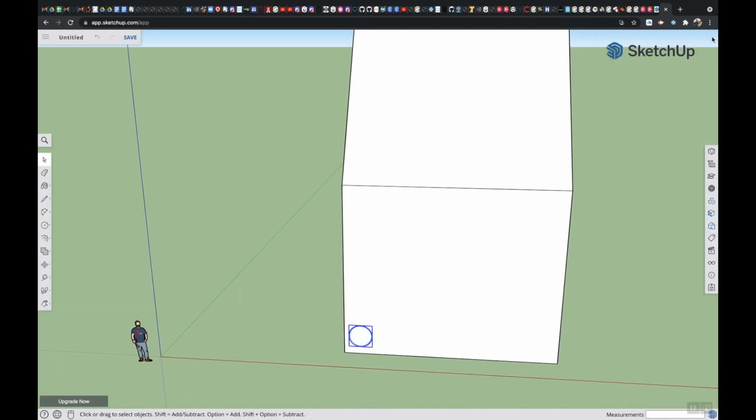Once you've done that, take the move tool and move this all the way across. As you do that, since you're using Windows, you're going to use Control, and I think for Mac you use Option. I'm holding down the left button on my mouse still. I just clicked Option for Mac. If it is Windows, you click Control. Then release. After that, type /, watch the bottom right hand corner, put 5 and hit enter.